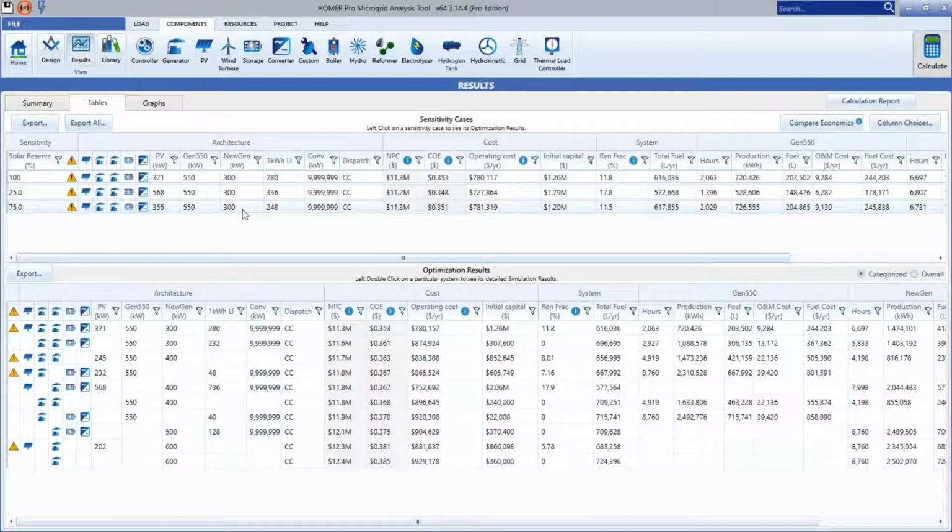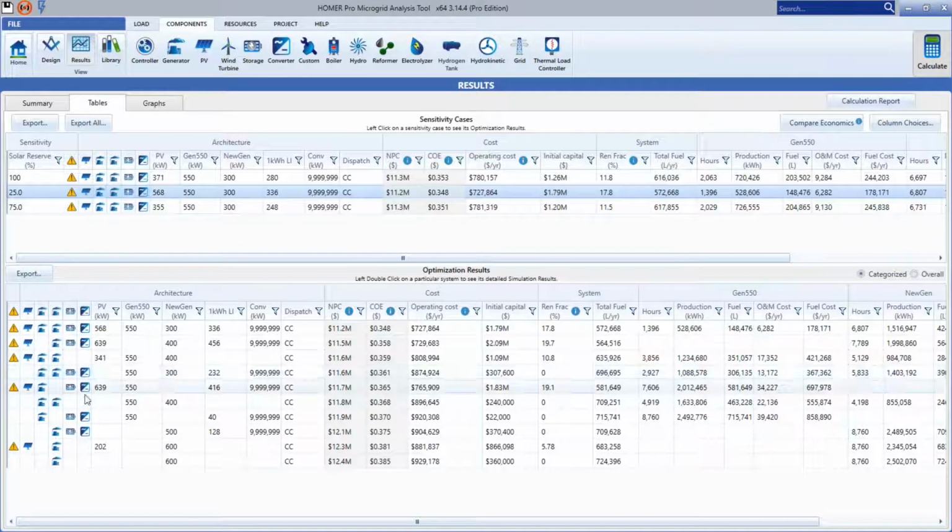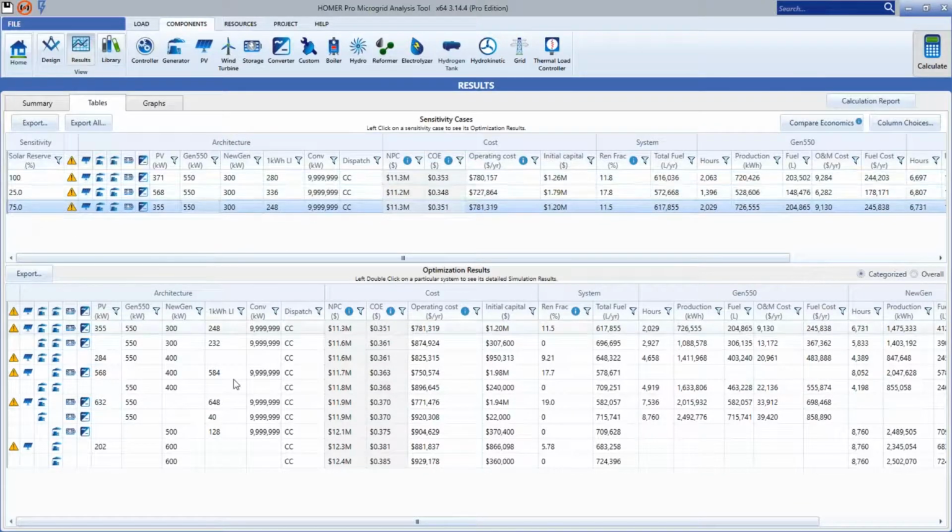Okay, so bear in mind that if we have a 100% requirement, because of that requirement, there is no system here that runs totally on solar because of the 100% requirement on the reserve. That means you cannot really use solar alone. But if we only require 25%, then it still has required capacity, because having a large system will not be economically viable. So here, the reserve requirement is really a determining factor for sizing the renewable variable sources, and also the capacities of the gensets that will support that reserve requirement.